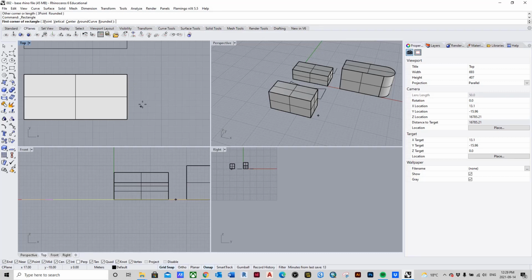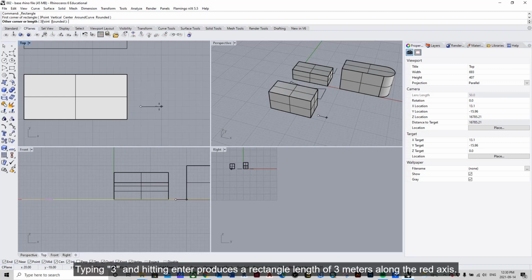Let's say we want to draw a smaller volume that's 3 meters by 3 meters by 3 meters in height. We select a point, and then as you can see, as we drag the rectangle tool, it drags along with us. Now, thanks to the fact that we know that we're in meters, when you check down here, you can see what units we're in. If you want to produce a precise surface area measurement, we're going to try just typing. We'll start with just typing 3 and hitting enter. Now look at that. That's now established.